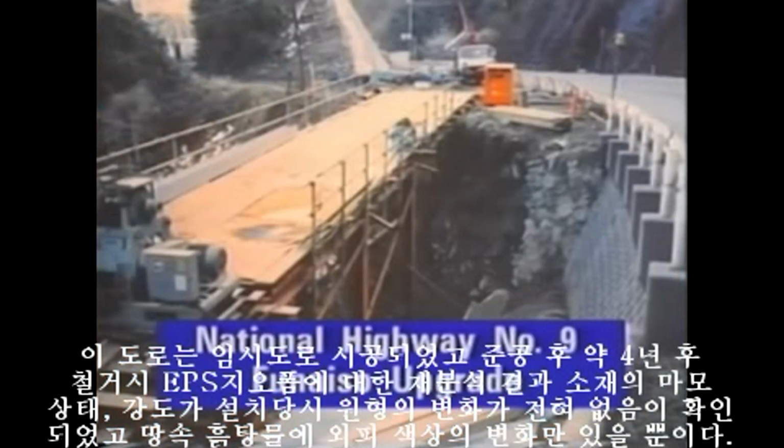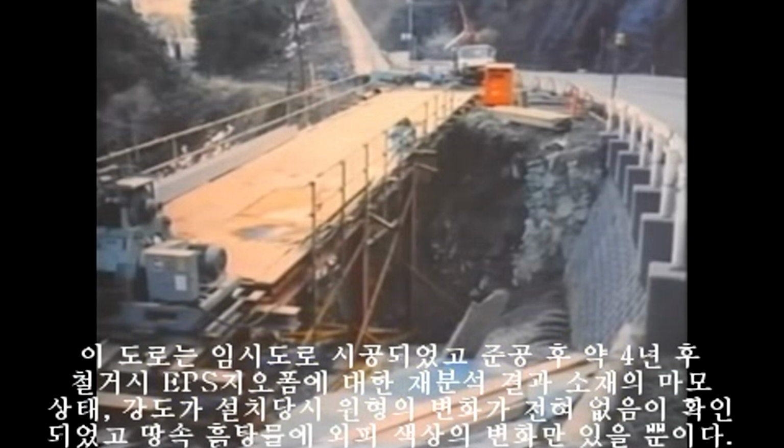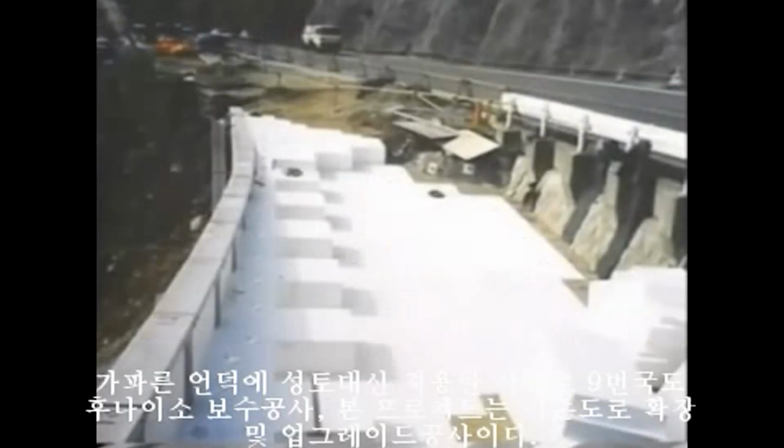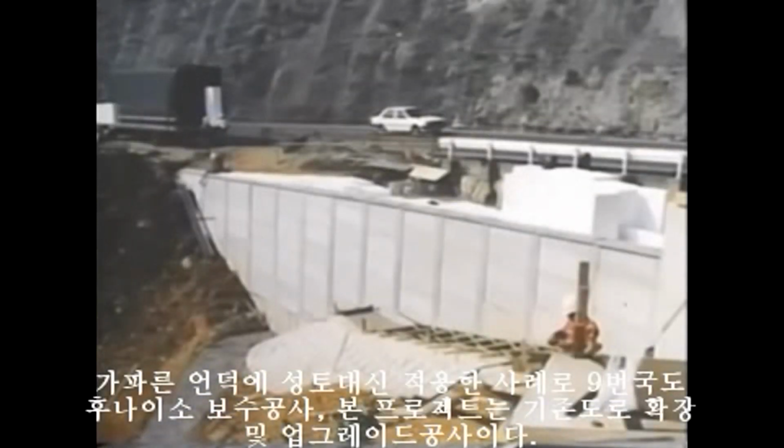In the expansion and improvement project at this 2-lane highway, engineers had to contend with steep topography and continuous sharp curves. The site was evaluated and was considered to be too difficult and expensive for conventional construction methods. Geofoam EPS was utilized to minimize traffic congestion during construction, speeding the actual construction time and eliminating the need for large construction equipment.